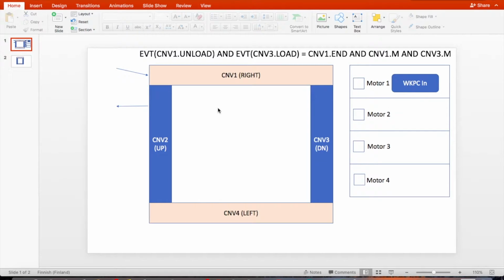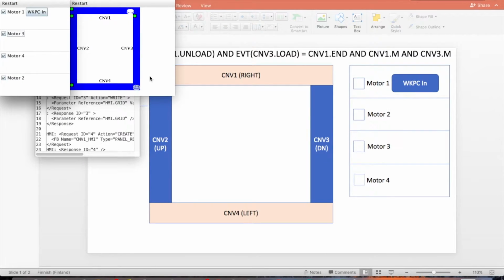Then on the lower level we need control of the motors. There shouldn't be any more signals coming from the HMI, but from the controller layer as we would create it. The basic idea could be that if a previous conveyor sees that the next conveyor has a workpiece, it won't try to push it to the next conveyor, as for example happens currently over here.